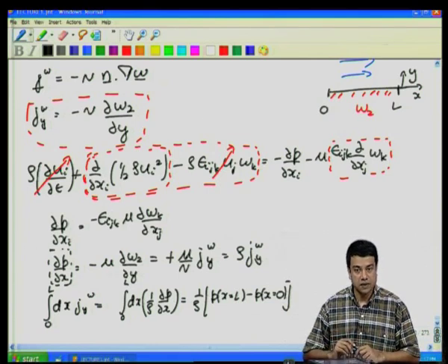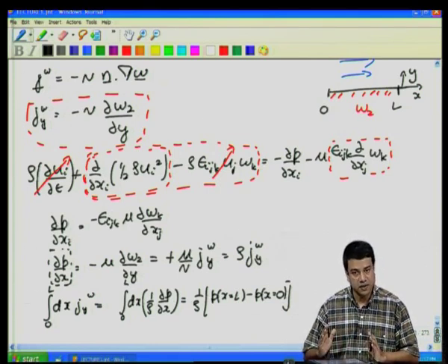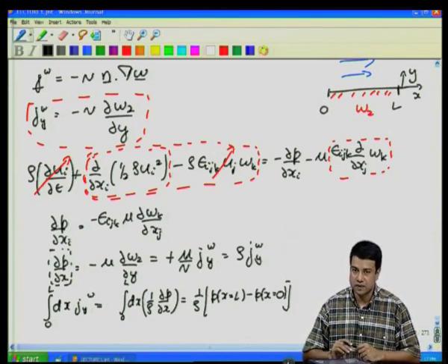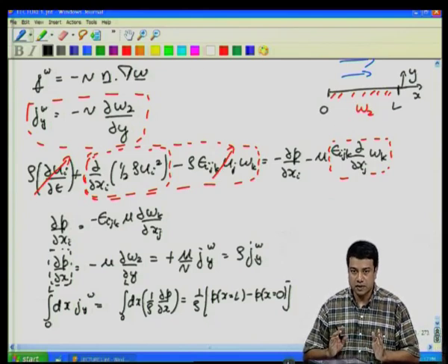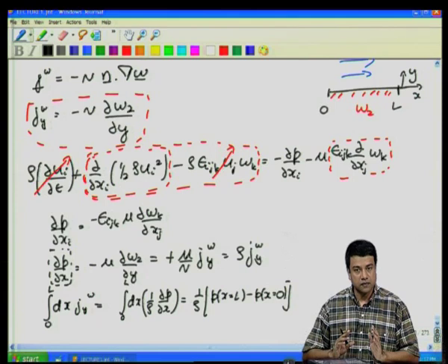So, only in the case where you have a pressure driven flow, where there is a pressure difference between the two ends, will you have a net vorticity flux coming out of the surface. If the pressure at the two ends is the same, even though there may be pressure gradients in between, the net amount of vorticity that is coming out has to be equal to 0.